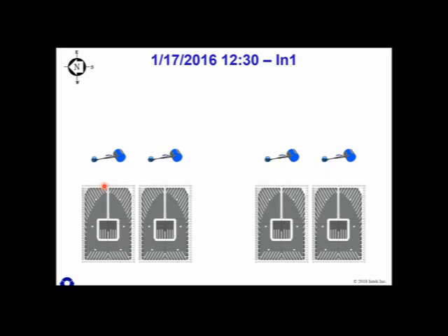And this is what the unit looks like. This is the two bundle arrangement. They've got two shells on this very large 800 megawatt unit. So there's a shell here. There's another shell here. And we put re-evacs on each one of their air offtakes to try and solve their problem for them.